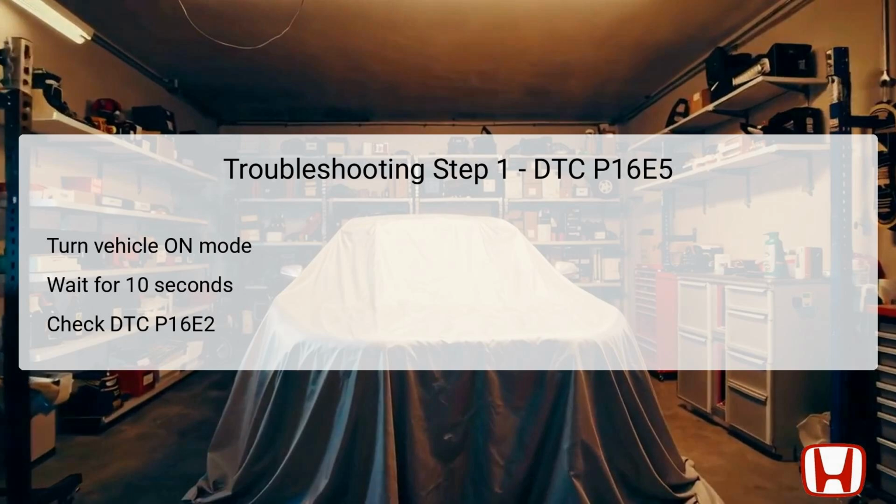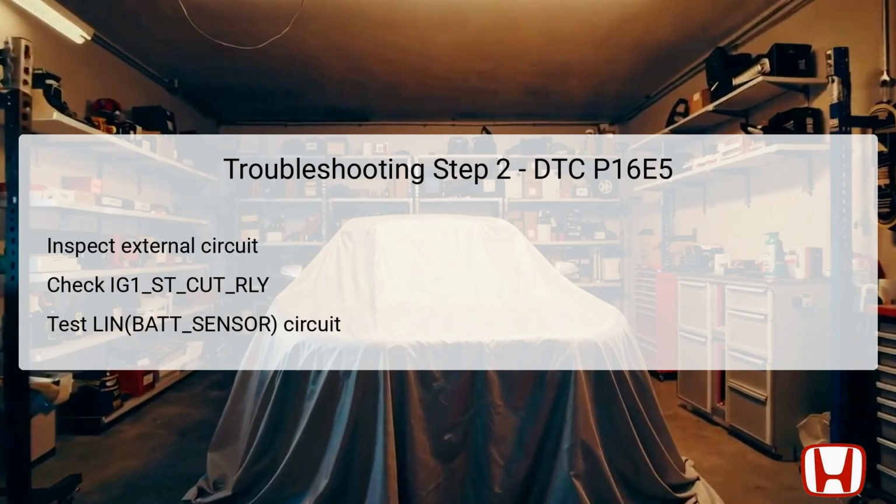If DTC P16E2 is present, it may necessitate immediate investigation before continuing with P16E5's diagnostics, as resolving interconnected issues can streamline the troubleshooting process. In the second step of troubleshooting DTC P16E5, focus your attention on inspecting the external circuit components primarily connected to the LIN, Local Interconnect Network.